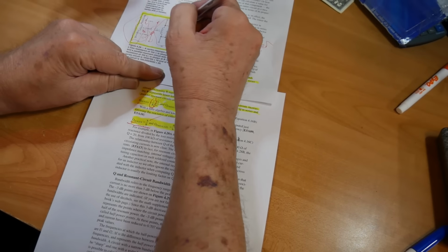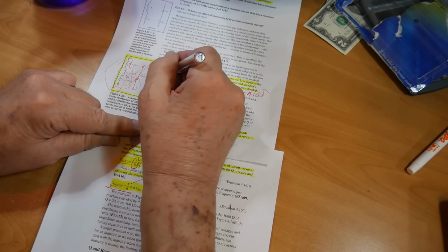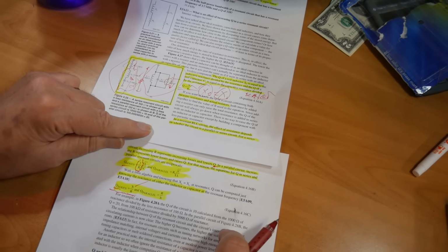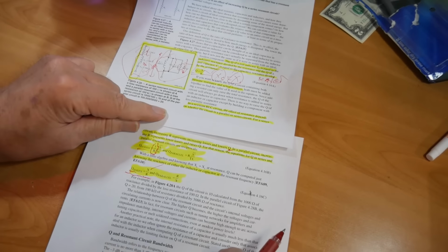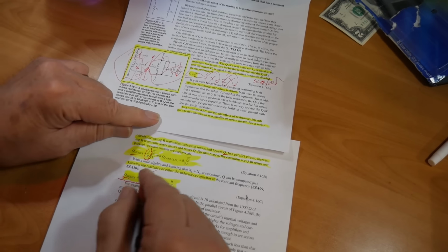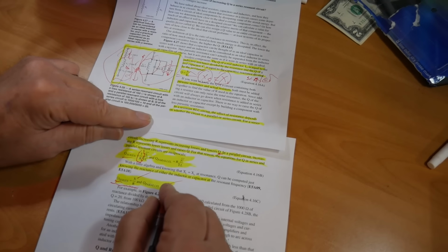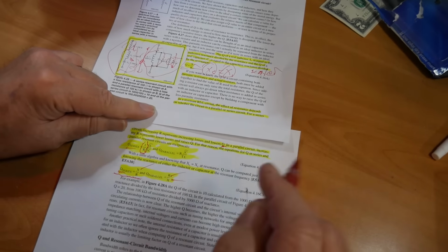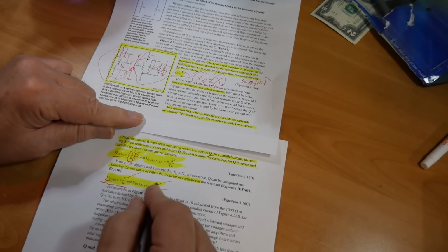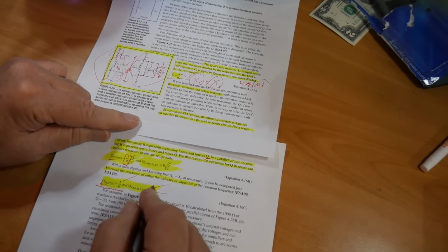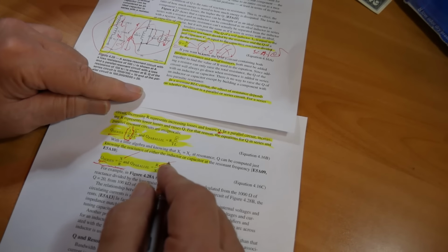If it's in parallel and you increase this resistance, then that means there's less current flowing through here. Okay? So the circuit depends more on just the reactive components in parallel. Now, as you want the R to go up, and the X is whatever it is that works for you to give you a reactive circuit, the resistance does not enter into the frequency of the reactive circuit. It is just losses in the circuit.